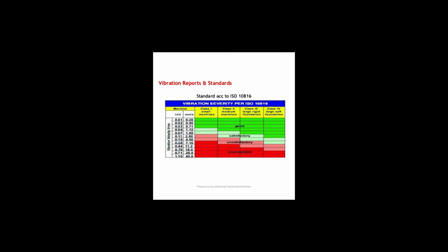Now I will talk about the vibration standard for lathe machine. Here we have a table for vibration severity criteria, or vibration standard, for turning machine or lathe machine. It shows us root mean square overall velocity level measured in 100 Hz bandwidth. On the left side of the table we have velocity in millimeter per second, and on the right side we have velocity in inch per second.